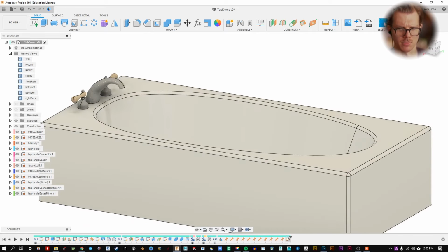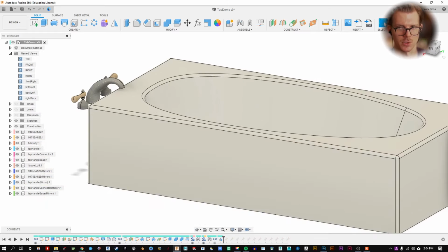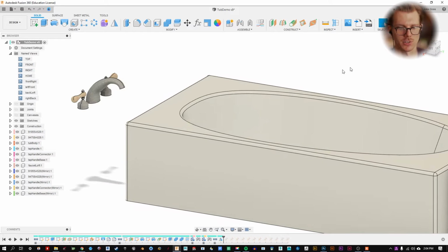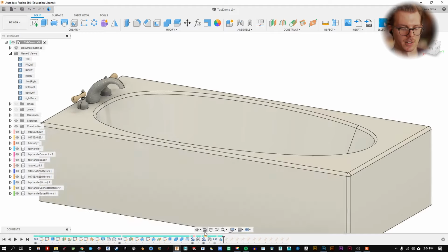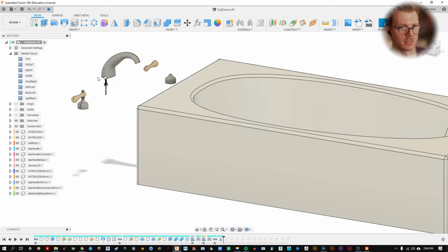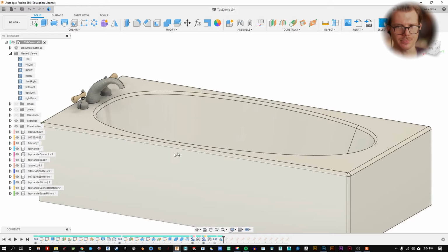Now, because Fusion is recording history in this mode, if you were to click and drag something, there's this over here that says capture position or revert. So it's really not remembering that. Say you do a bunch of work and all these things are all over the place. You can hit revert, and it doesn't add a history item because it's recorded that there was no movement. So this is not in any sense of time. It's not the end of the world, but it might be annoying as we're working. So we could ground these.